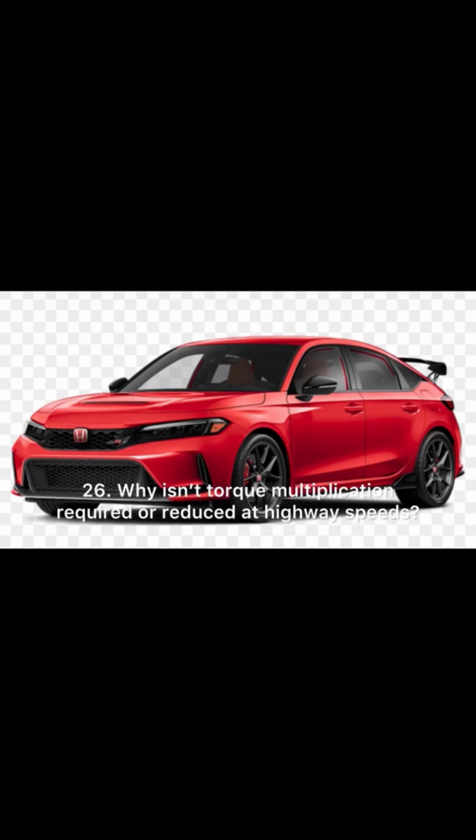26. Why isn't torque multiplication required or reduced at highway speeds? Momentum or inertia will carry the vehicle through the load condition. 27. Whenever the gear ratio is less than 1:1, it is called overdrive.